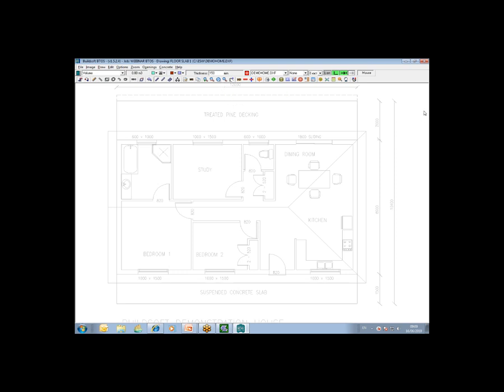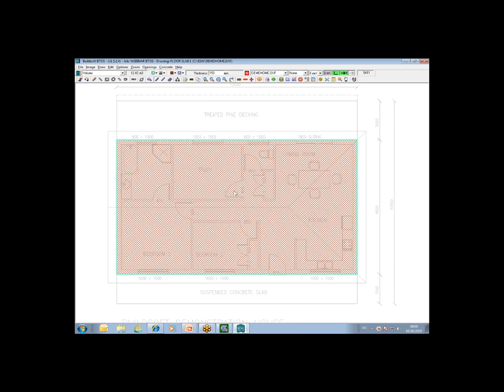And again, zoom in on the section of the drawing that you want to deal with. Now, this is zoomed in quite well, so I actually probably don't need to zoom in on this one. So what I'll do is go to my first point, click, second click, and then again, you cannot manually join back to the first point, so you hit J on the keyboard, and it will join it automatically for you.